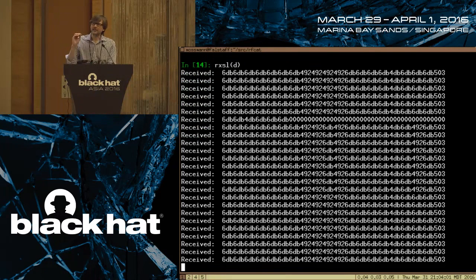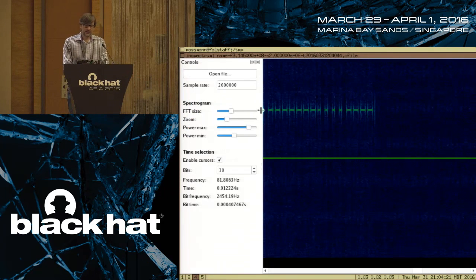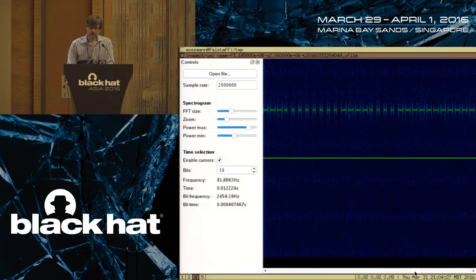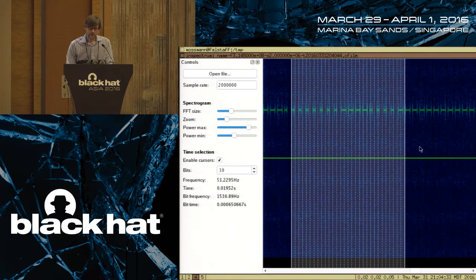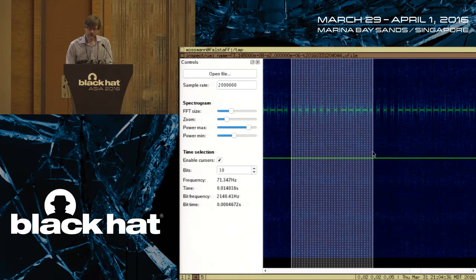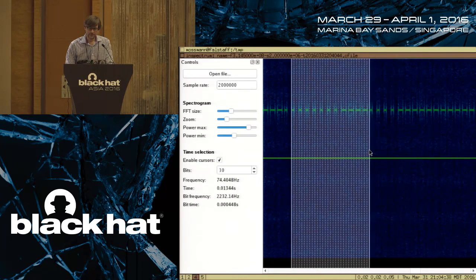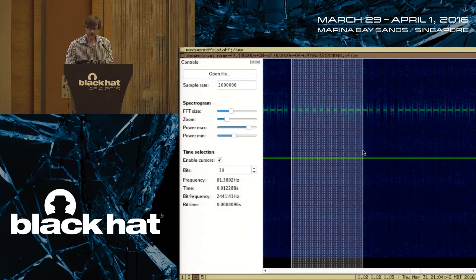Now what I want to do is actually decode the pulse width modulation. So instead of 110, 110, 110, I want to see that that's long, long, long, and 100 should be short. So I'm going to take those long pulses and represent them as a 1, and take the short pulses and represent them as a 0, or the other way around. Now, one way to think of that is, if I look here, if I were to, let's say, use my cursor here and line things up, you can see that, is that about right? Or there we go.